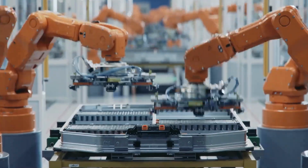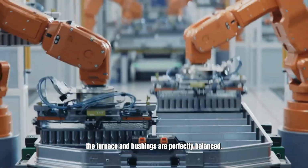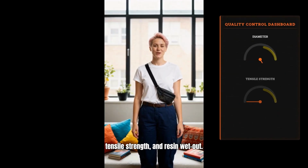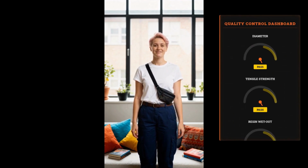Stability is everything. We monitor the process constantly to ensure the furnace and bushings are perfectly balanced. In the lab, we test for diameter, tensile strength, and resin wet out. Quality means the fiber performs correctly in the field.